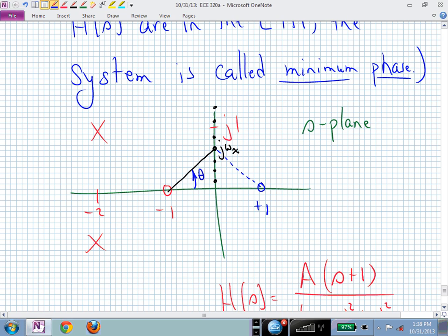I think that's the same. It's like Pythagorean theorem. Have the same distance horizontal, same vertical, a squared plus b squared, hypotenuse, same length, right? So the magnitude response looks the same if you have 0's exactly opposite the vertical axis in the right half plane versus the left half plane.